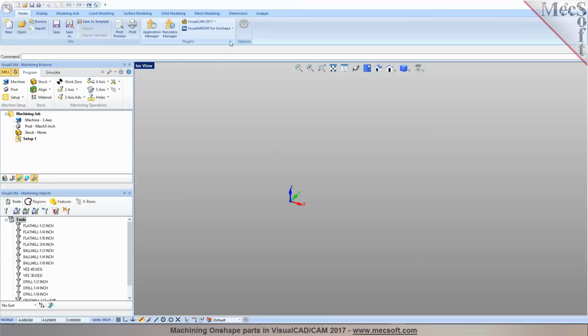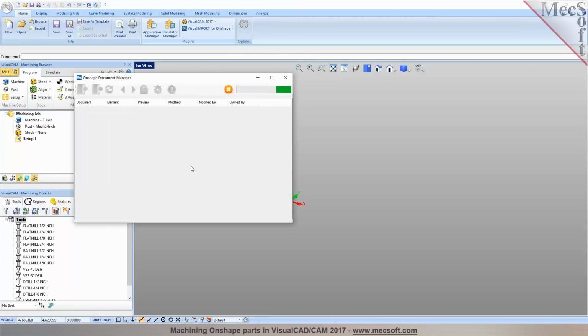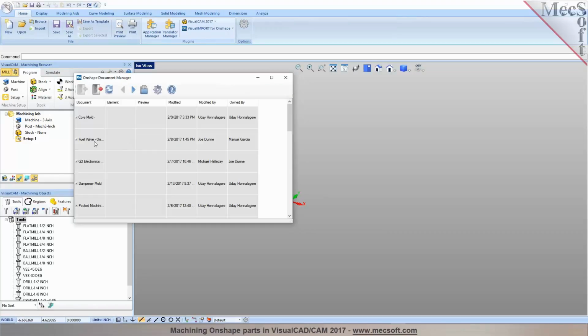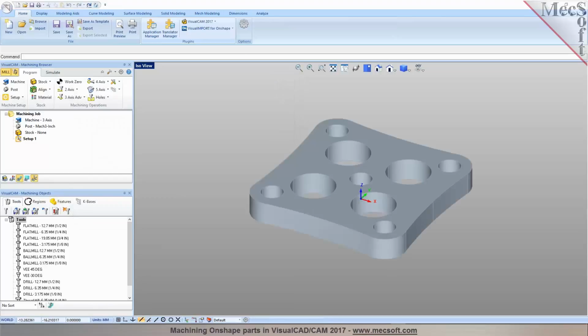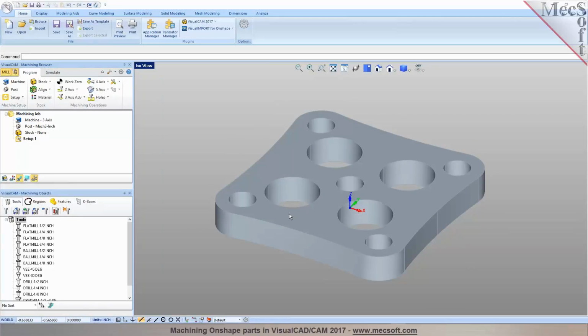So this is going to go through the process of loading the part from Onshape, right? It's going to locate the parts that you designed, and whatever changes you've done to the design, it'll update in the list, and now you can go back and pick the parts. I'm going to use the same part in here. I'll pick load. So the part is now being loaded. I'll switch the units to inches. Okay, now we got the part loaded in here.